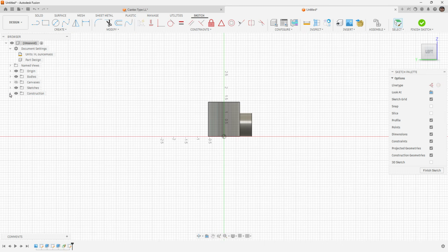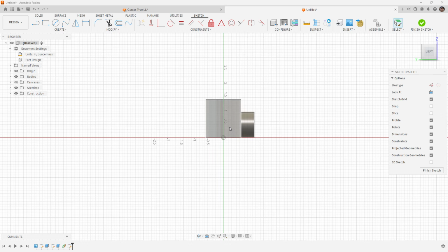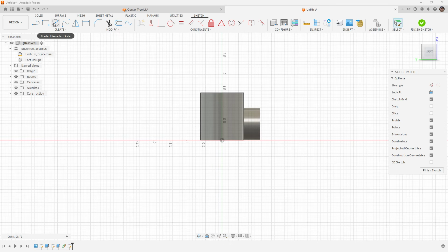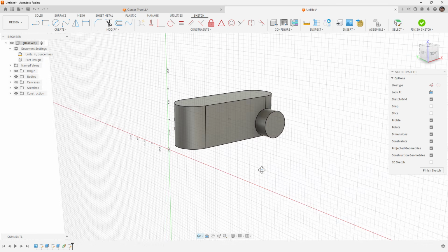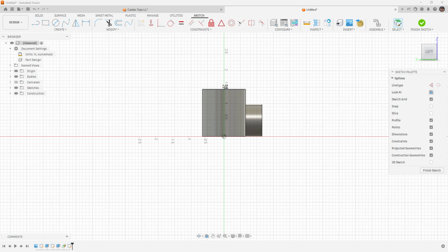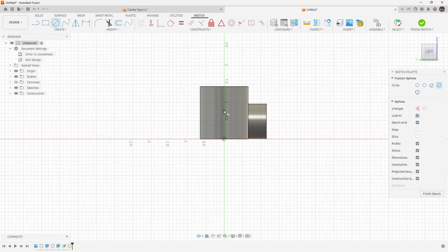Fusion is going to save that construction plane in a folder, very similar to Plasticity, where it saves it in that menu on the right-hand side if you save or store construction planes. What happens with Fusion in these scenarios is that the coordinate system gets pushed to our plane, so it's not always based at the origin. It's going to be based on the current plane. So we still have Y that we can use here. I want to snap to Y above the origin and come down and snap there.